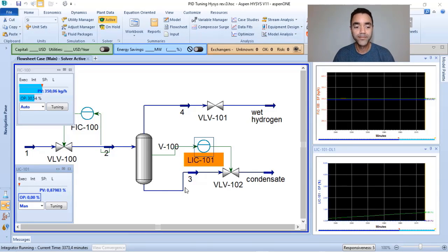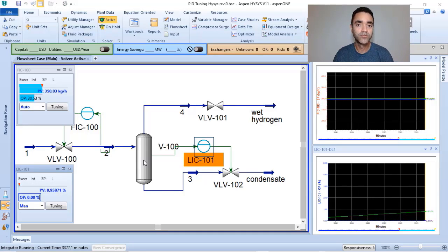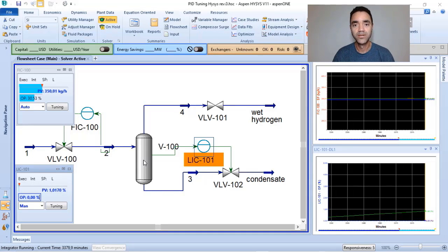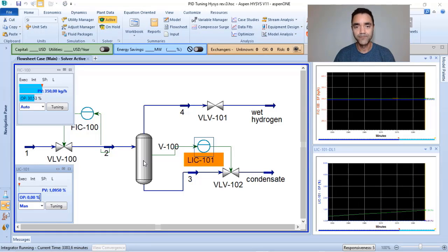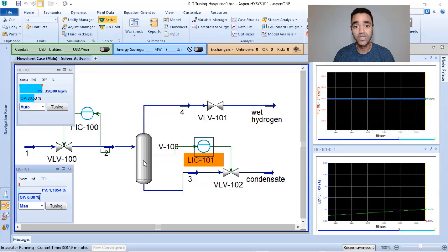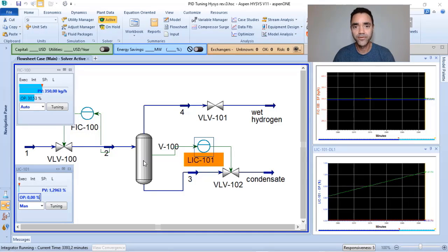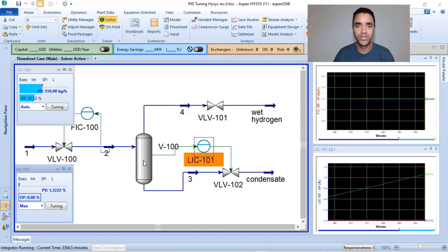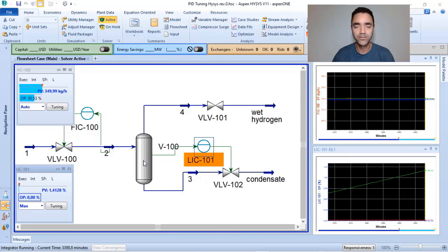And here we can imagine that this vessel separator is too big for the amount of liquid that we have in this system. The calculation or the sizing of a vessel separator depends on two things. The first one is the amount of gas that is going in, because you need to have the velocity that goes to the vessel separator.